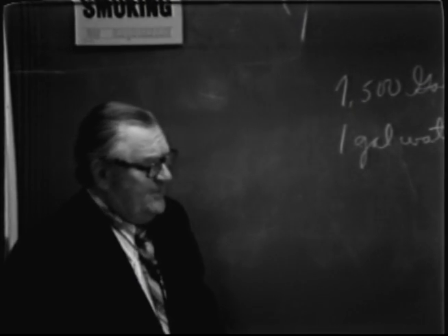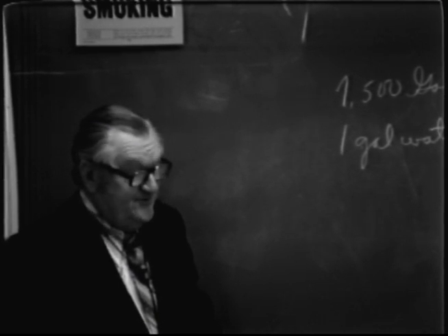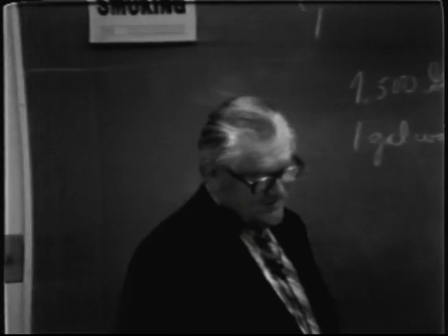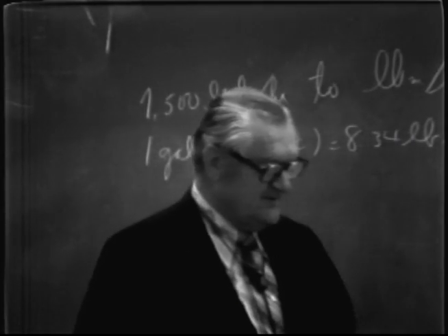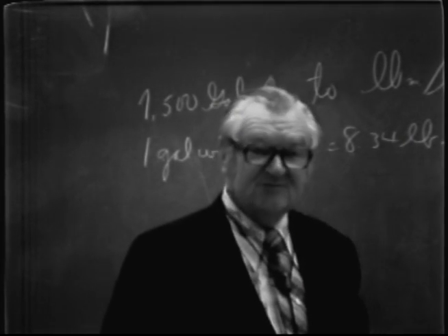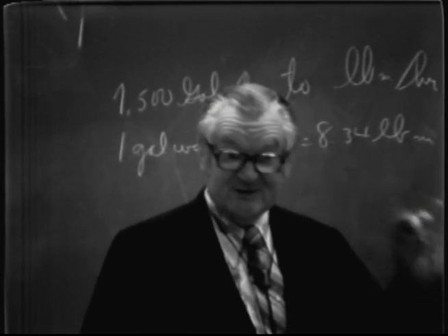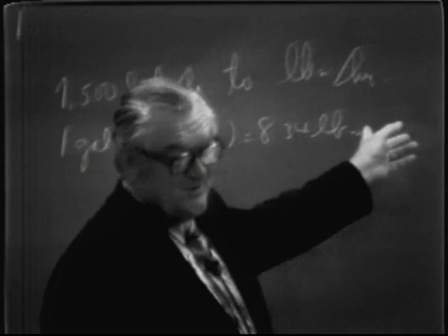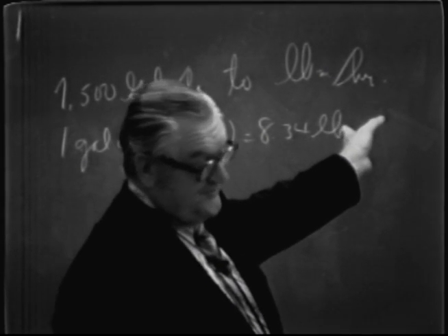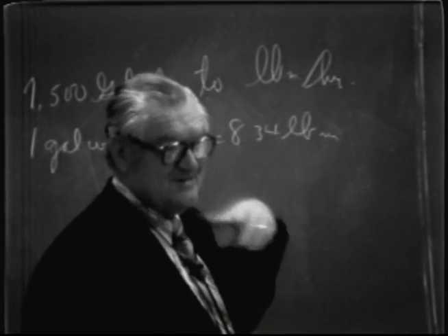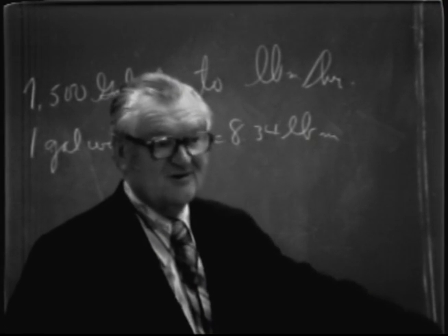But as I said once before, when you're working problems, if some bit of information is omitted or not available to make a completely rigorous solution, you just make a reasonable assumption. For example, you assume some temperature for this feed, and the easiest one to take is 60 degrees Fahrenheit, because that's the basis of our measurement of volume percent alcohol.